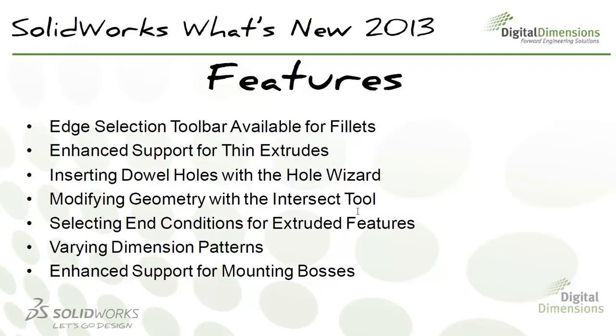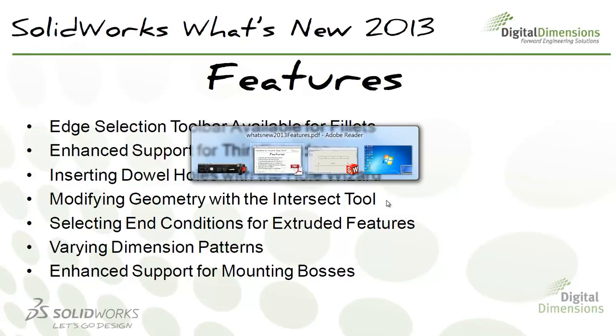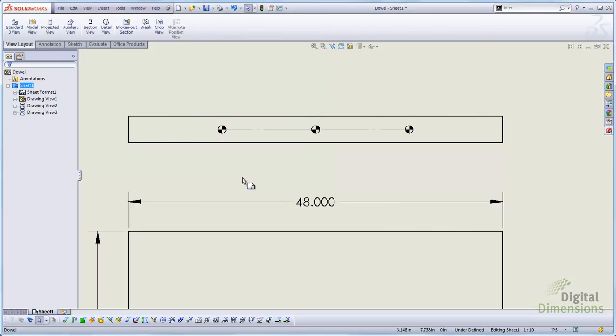So I really think of this command as a cut with surface, replace face, split, and the combine bodies feature all rolled into one. So this can save you 1, 2, 3, up to maybe 4 features because you can do so much with it and all in one feature. So let's go back to SOLIDWORKS and I can show you some of these examples.